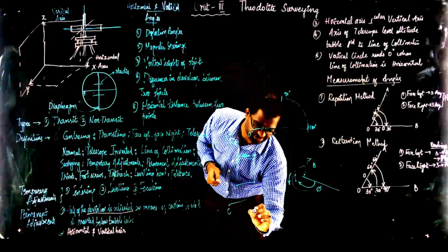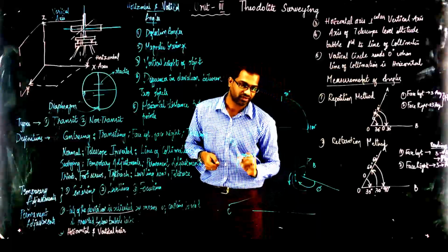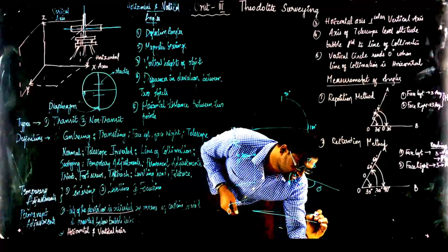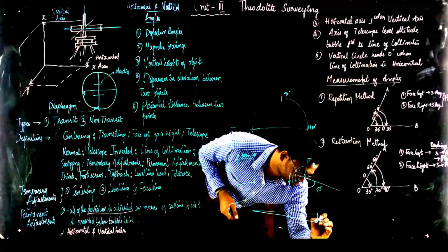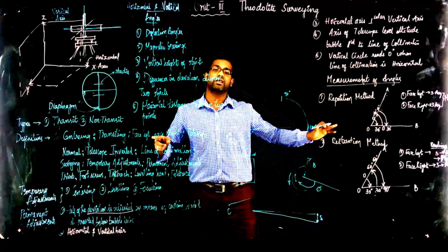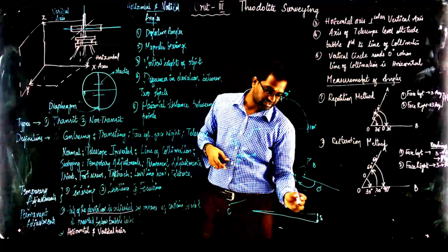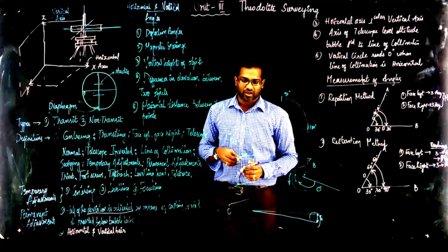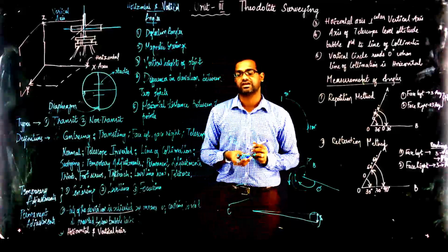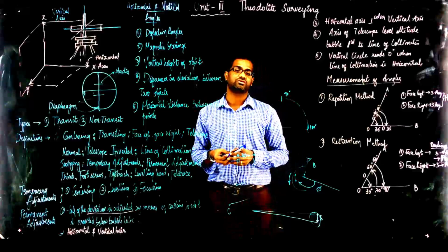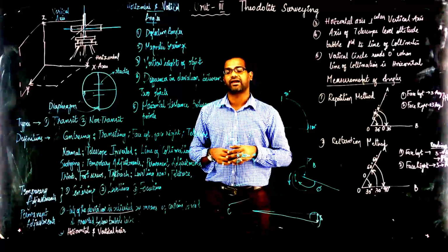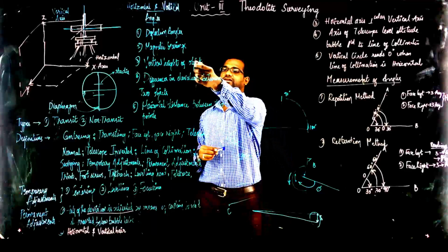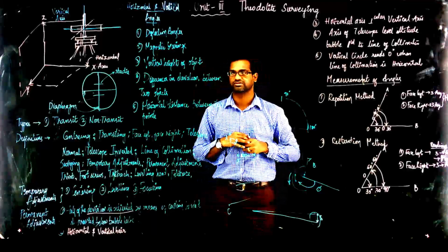Now, even if this is the perfect 90 degrees line and even a small change is there, the error gradually increases, and you have a big error as the length increases. This makes things very complicated when you have too many errors in a building. So the theodolite compensates for these errors because it is specially designed to estimate the angles between two points. Thereby, you can apply trigonometrical principles to calculate the vertical and horizontal distance between two points.